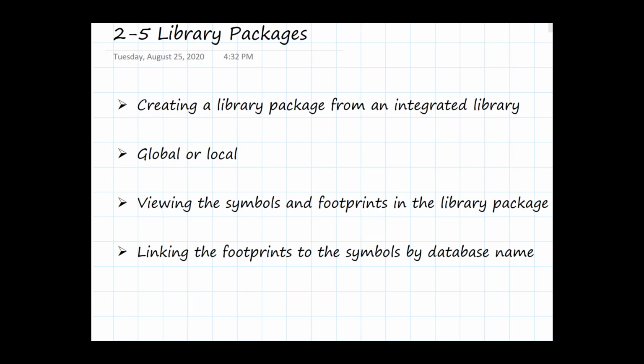In this video, I'm going to introduce you to library packages. It is a distinctly different library than the integrated library that we've talked about so far. And I'm going to show you how we can take an existing integrated library, that's that closed database, and crack it open to expose the symbols and the footprints.